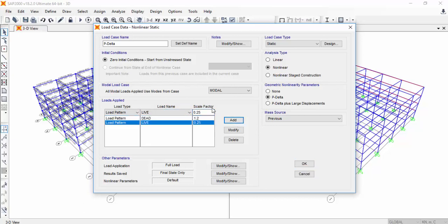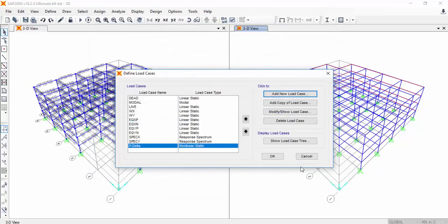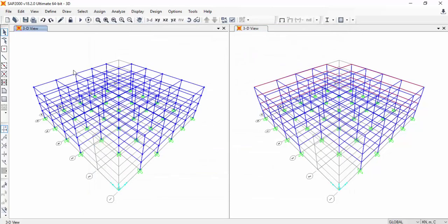We are not exactly very much interested in doing this kind of combination analysis. Rather, we are only interested in extracting the stiffness from the P delta analysis to include the effect of axial loads on stiffness. Take a note that design codes recommend to reduce the flexural stiffness of beams, columns, walls, slabs when we are doing a P delta analysis. So how do we activate it here?